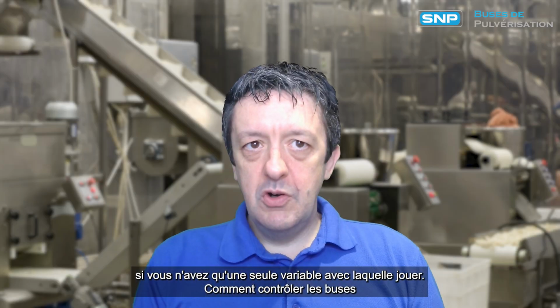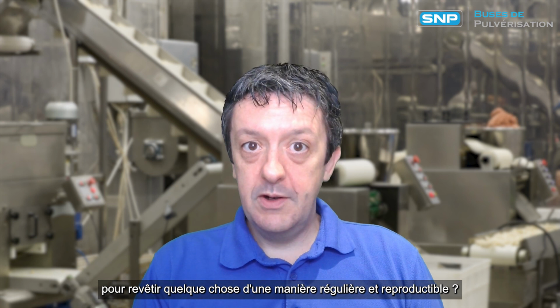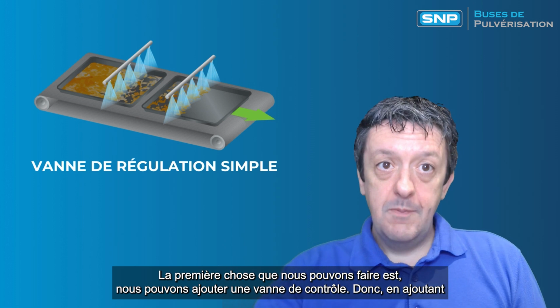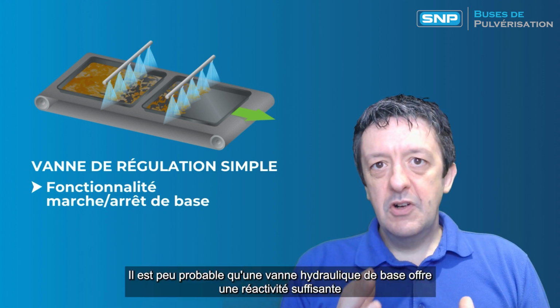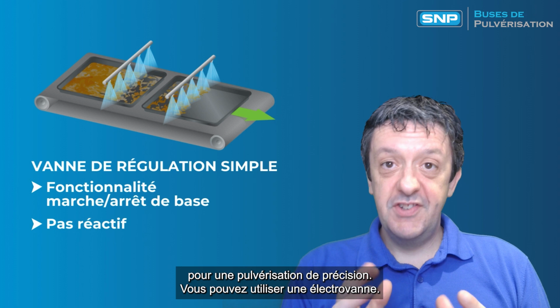How do we control a nozzle, for example, on a coating line where we want to get the exact amount on target to coat something in a regular, repeatable way? So the first thing we can do is add a control valve. Adding a shut-off valve near the nozzle can help control the on-off cycle. A basic hydraulic valve is unlikely to offer enough responsiveness for precision spraying.